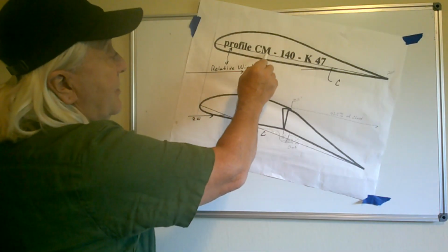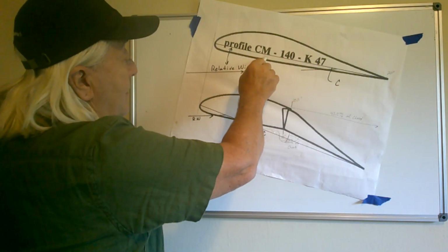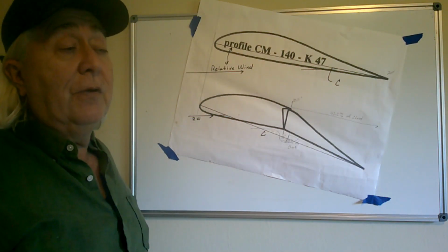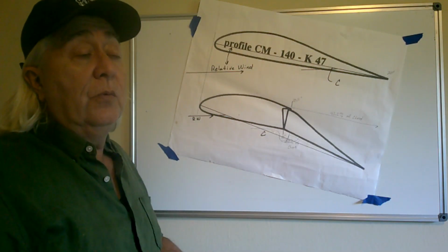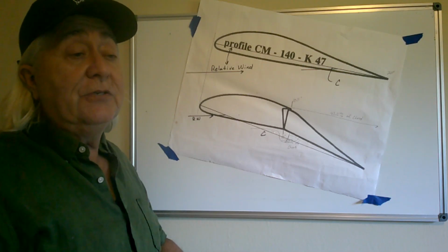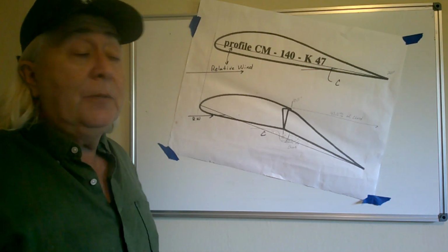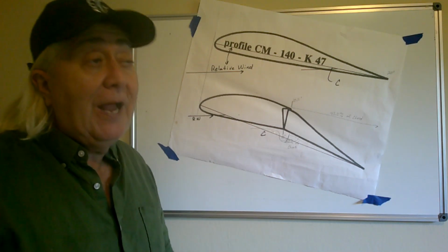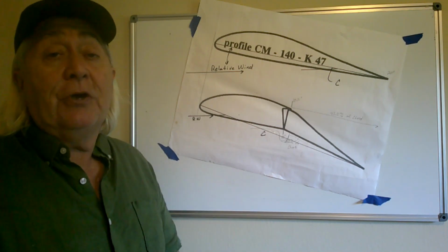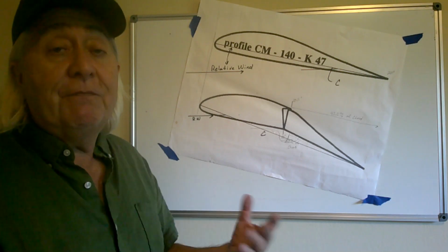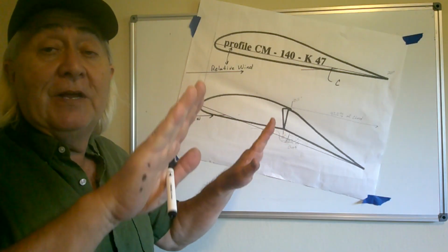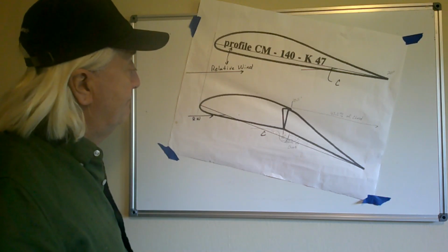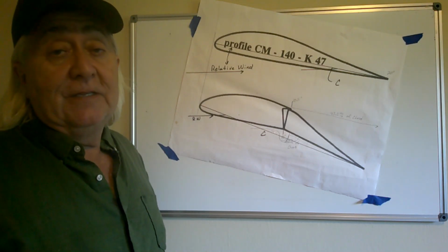And if this is already close to stall, well, this will go right past stall, just like I showed you in the data. If he was trying to slow up for landing and he's working around the stall area because he's trying to get it slowed up and he drops a little bit more flap, boom, stalled wing. And if your flap is 2/3 of your wing, you just stalled 2/3 of your wing and you fall out of the sky, especially if the elevons are up and not generating any lift out at the tips. Heck of a deal, isn't it?